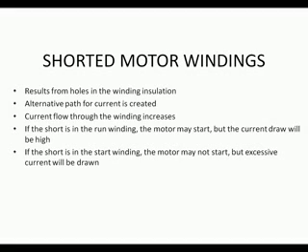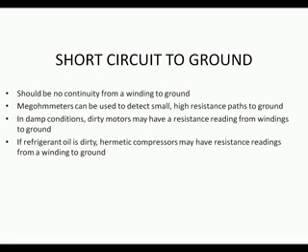If I took a reading from start to run, I would have an OL, or an infinite reading. Then I would take a reading from start to L1. Again, I'm going to have an infinite reading. Make sure you remove any capacitors or components before you take these resistance readings. Shorted motor windings result from holes in the winding insulation. It allows an alternate path for current to be created.